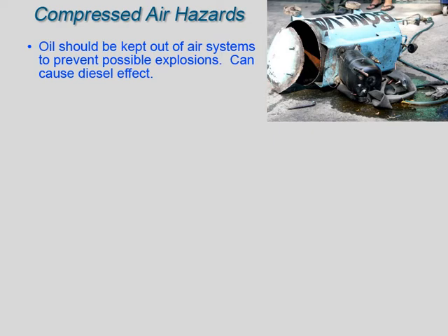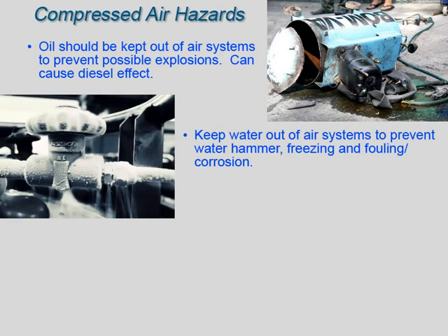We know that if we compress air, it will heat up. In the opposite case, when a gas expands, the temperature will drop. If a compressed air line is suddenly depressurized, there is potential to form ice crystals at the point of the pressure drop. Ice formation may also occur when opening large air valves rapidly and could cause them to become blocked. The higher the air pressure and the higher the air moisture content, the more likely ice formation will be.